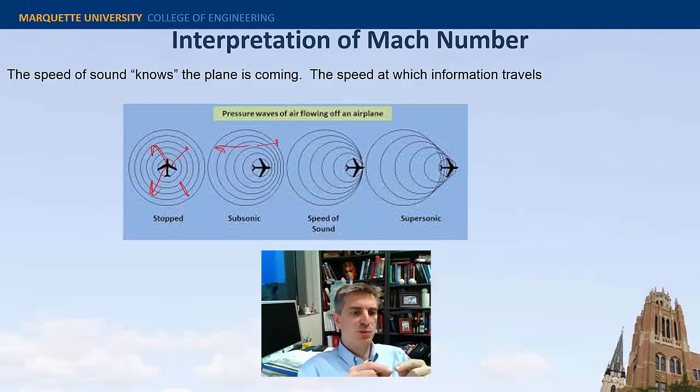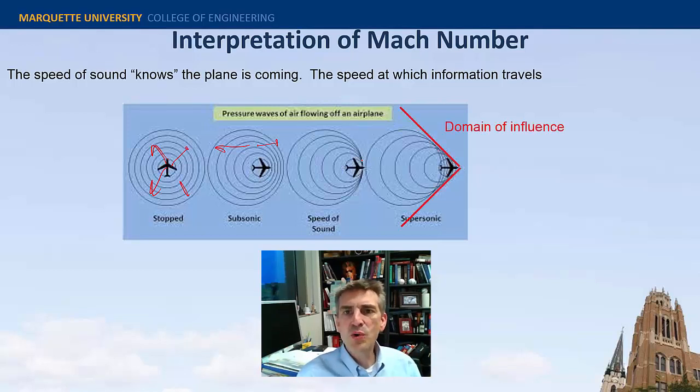So eventually, at supersonic speeds, the molecule, which would typically get a signal from the coming plane via the sound speed, hey, something's coming, you better start getting out of the way. When you get to sound speeds of 1 and greater, that molecule doesn't have a chance to get out of the way. The information isn't propagating back upstream, and so you form kind of this cone of influence, right? It's really a cone of silence where information is not crossing across that cone until much later, until after the plane passes.